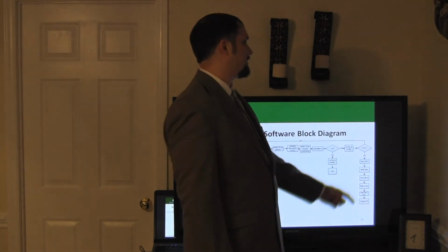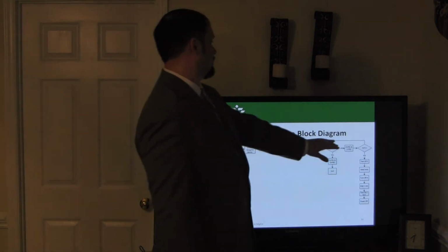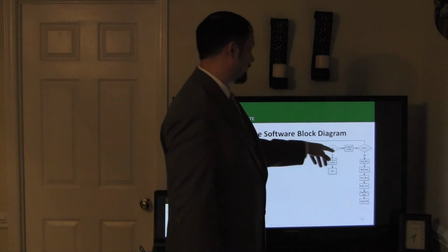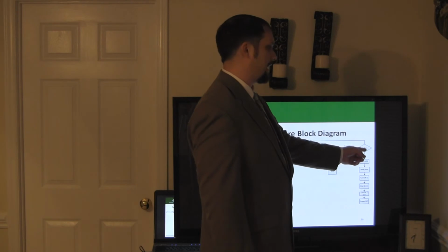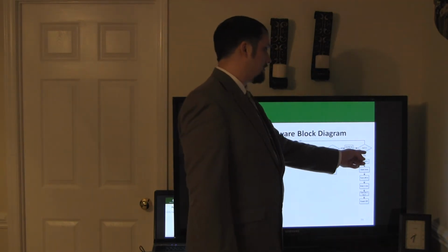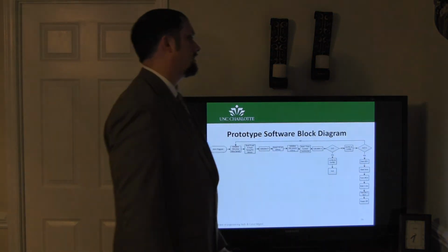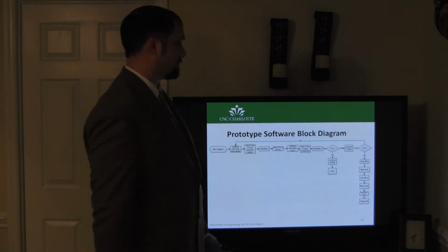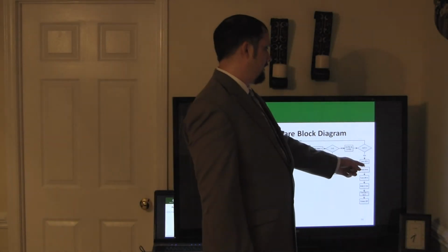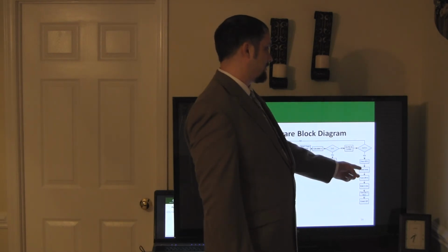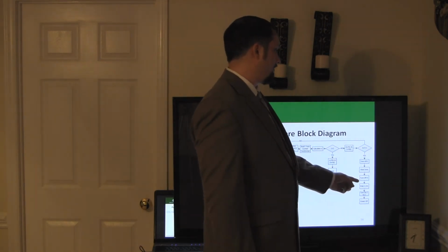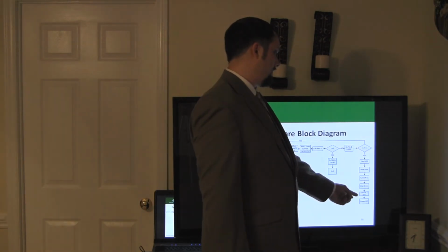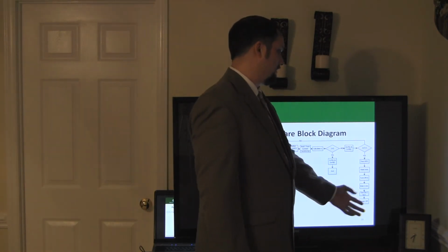Now, at any point in time after the ADC and the reading of the relative humidity and temperature sensor and calculating the absolute humidity, if the absolute humidity is ever equal to what it was when it first started, then we wait 5 minutes, turn off E, wait 5 minutes, turn off O, and then we wait a minute and turn on E and O, and then we power off.